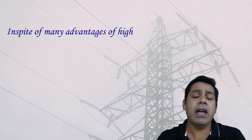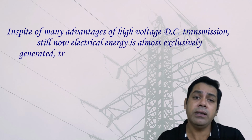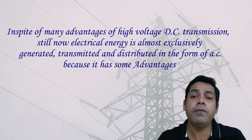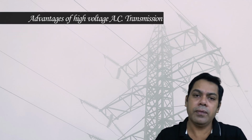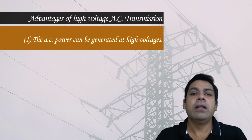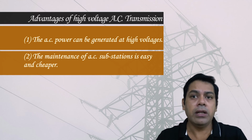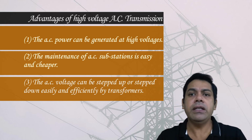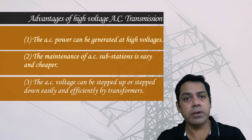In spite of many advantages of high voltage DC transmission, still now electrical energy is almost exclusively generated, transmitted and distributed in the form of AC because it has some advantages. Let us look these advantages. Number 1, the AC power can be generated at high voltages. Number 2, the maintenance of AC substation is easy and cheaper. Number 3, the AC voltage can be stepped up or stepped down easily and efficiently by transformers.